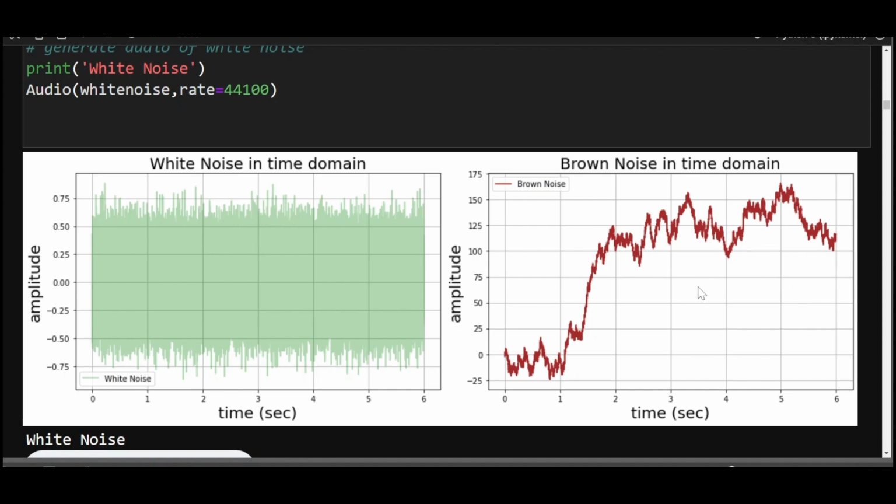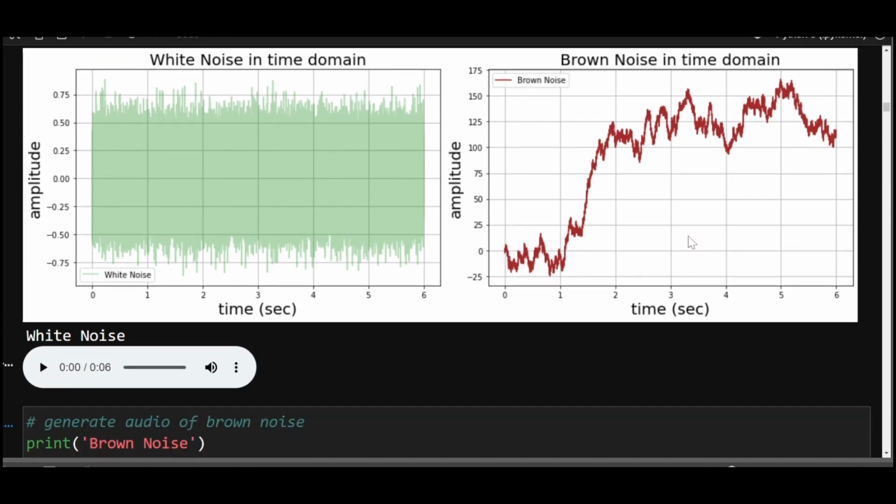And these kind of signals, they are problematic signals. They cannot be handled through linear filtering theory. Linear filters are very good at handling white noise, but they are not so good at handling signals like the brown noise. For that reason, we have statistical filters like least mean squares or recursive least squares. Normal filters like sliding window, sliding median, or FIR, IIR kinds of filters are very poor at handling such noise.